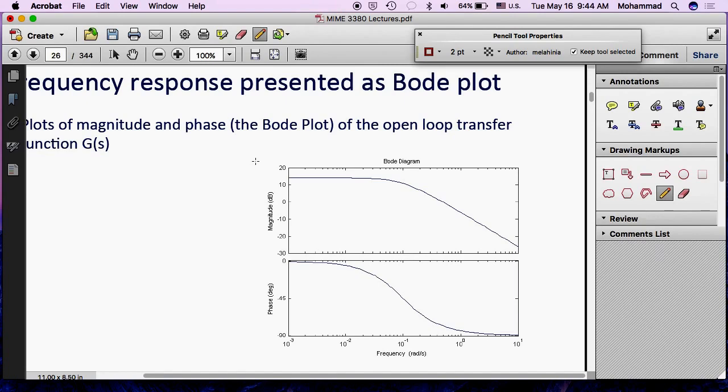Bode plot is a way of seeing that. Now, you can look at the response to a single sinusoidal input once, and then go to another sinusoidal input and look at that response, and yet another one, and another one. How many plots do you have to look at to get to the characteristic of the response? Hundreds. The first one happened at 1 hertz, the second one at 2 hertz, the other one at half a hertz, the other one at 1/5 of a hertz, another one at 100 hertz. Do you see my point? Bode plot captures all of that information into a single plot.